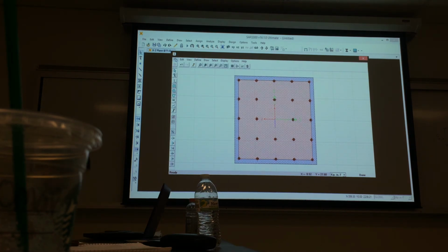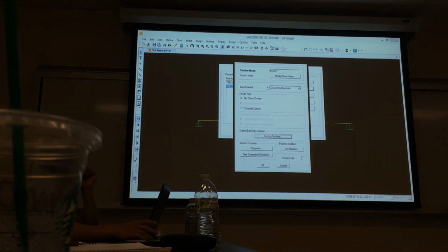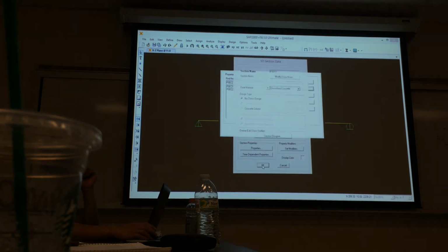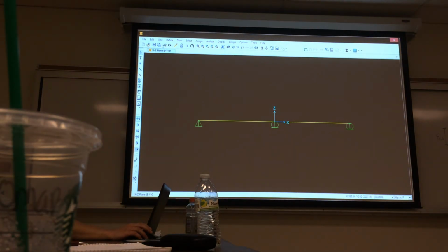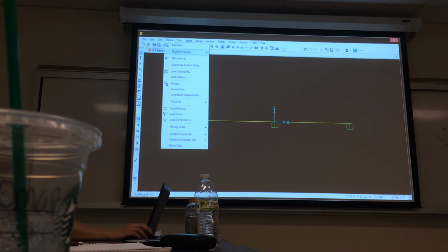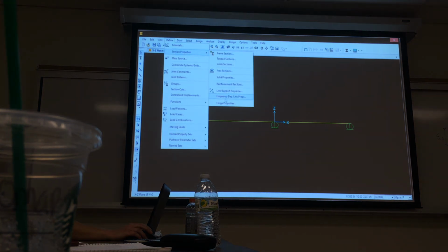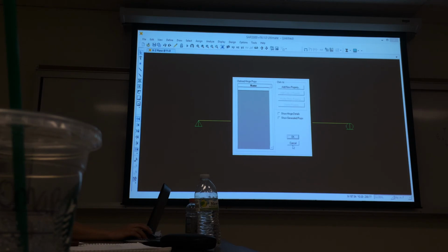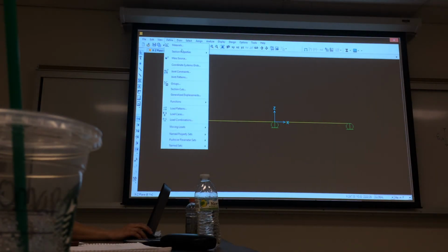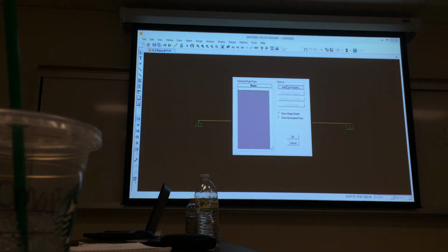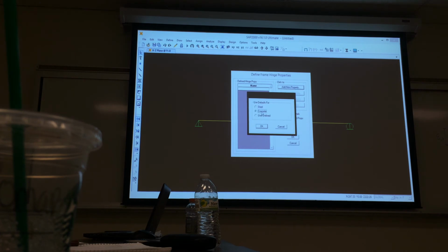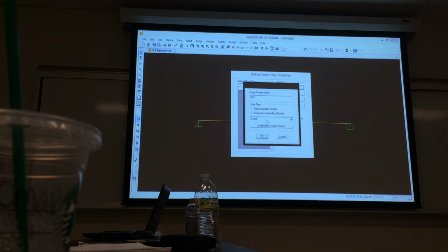And that's essentially how you do moment curvature analysis in SAP. You could then use those properties and some of the different things. Let's see something here. So if you go to find section properties, you go down to hinge properties. Let's say hinge.